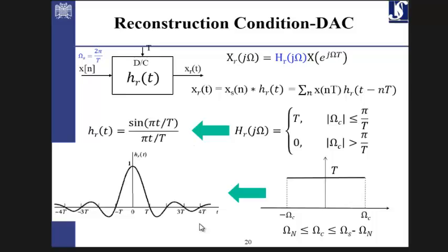Representation of this in the time domain is something like that. In the frequency domain is something like that. The graphical form is something like that. So omega c and minus omega c are the cutoff frequencies. That's the gain. But this one in the time domain is a sinc function. That's the sinc function. That's the mathematical form for this sinc function, and the zeros of the sinc happen at T periods. These are multiples of T.